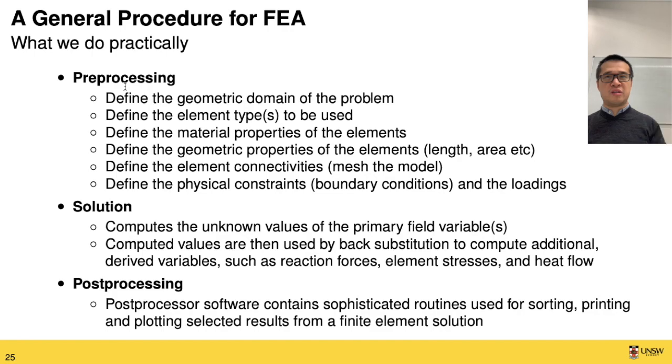Typically, you want to start with a lower degree of freedom. That will give you the answer much quicker because it requires less computational power. And once you have some general idea of, for example, the loading distribution on your shape, some parts of the shape might need more points to model them more accurately. In that case, you put more nodes at those specific points.